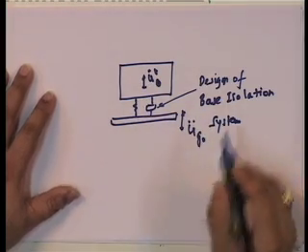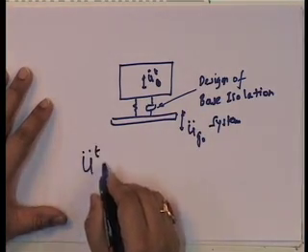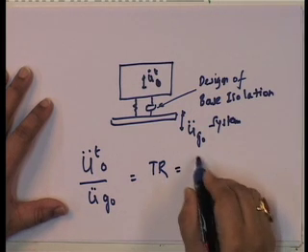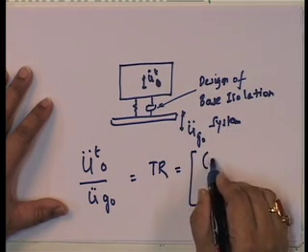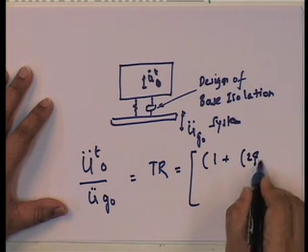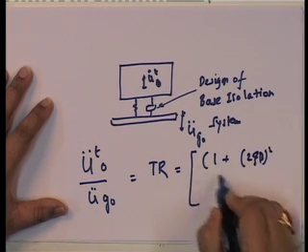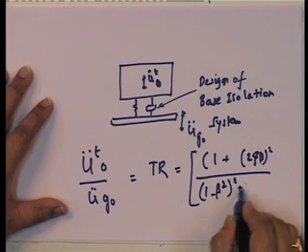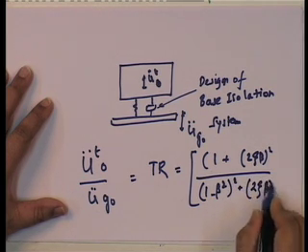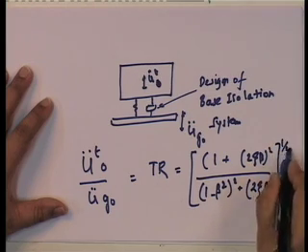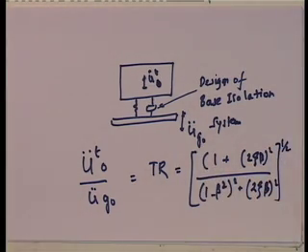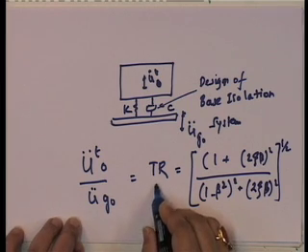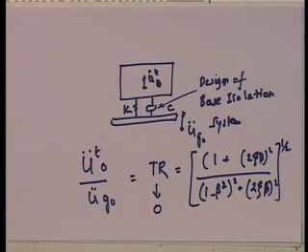So, this is a base isolation problem, and essentially this is the same as the transmissibility ratio, which is 1 plus 2 xi beta the whole squared upon 1 minus beta squared plus 2 xi beta the whole squared, under square root. So, this is the design of the base isolation. I have to design K and C such that the transmissibility ratio tends to 0. That is my design problem.